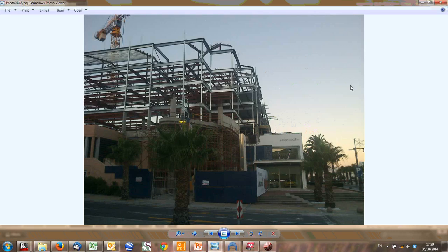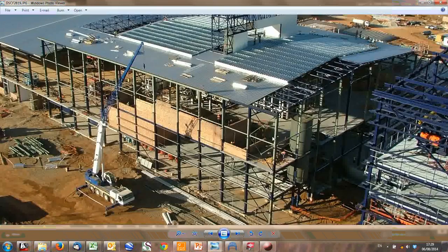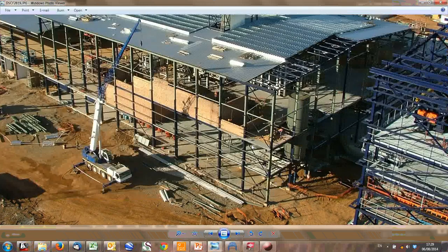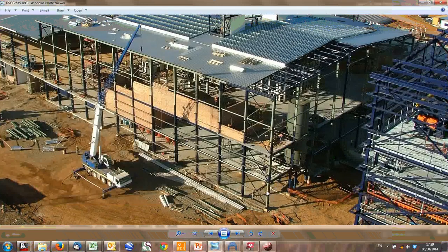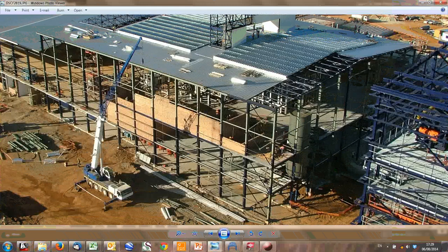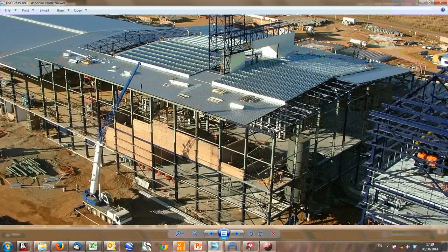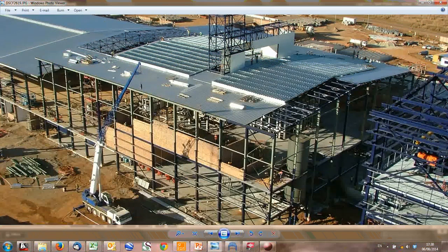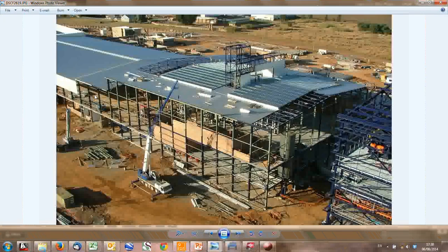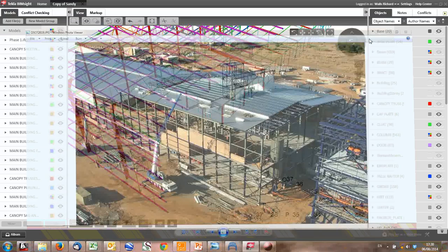We'll have a look at another side. It's the same picture. Here we go. Here's another structure. Multi-story. Here we've got concrete floors. A wind load comes along here, and here's your braces. This braces it out. And roof bracing, same story. Wind load goes up, wind load goes down, through the bracing down. Dead load, live load comes down your trusses, down your columns, down your trusses, down your columns. And this way you can really analyze an entire structure by breaking it up into simple components.